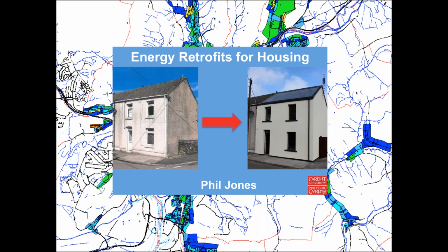They're all being monitored. Some of these are quite recent, so some of the latter ones I showed, we're only just retrofitting now, but they will all be monitored. The first 5 that we looked at, we haven't had any issues with those. I guess the only issue we had was with the batteries. Some of them we used lead acid batteries. At that time, they seemed to be the cost-effective way. In the meantime, the battery costs for lithium-ion have dropped probably by 50%, and the lead acid batteries didn't work. They deteriorated over time. They lost their charge, and they weren't really suitable. So we've gone back and replaced them with lithium-ion.